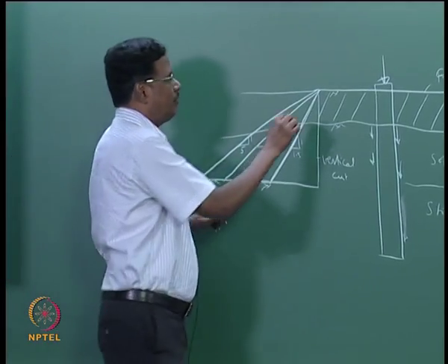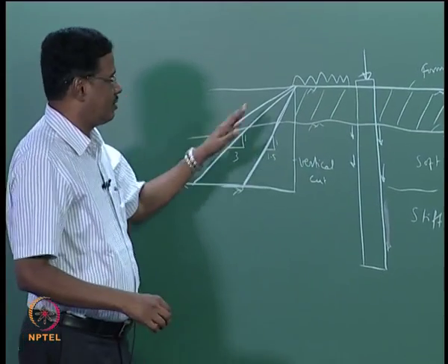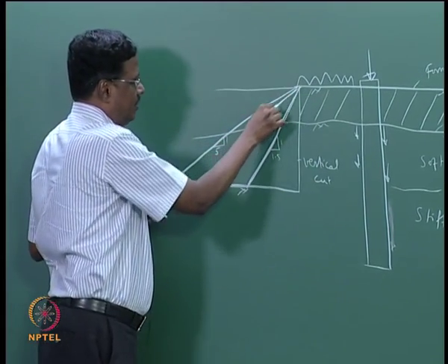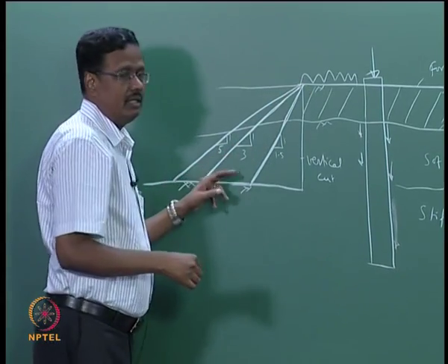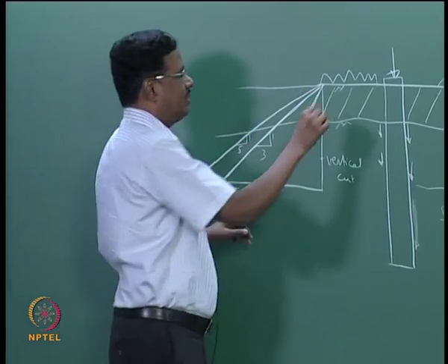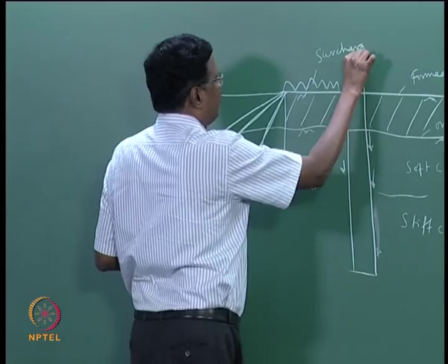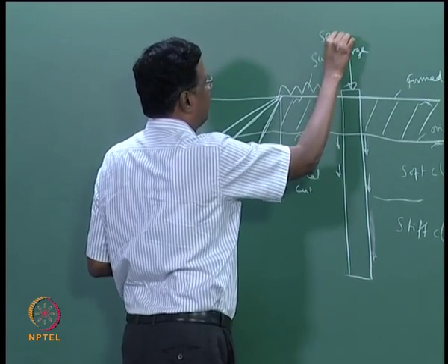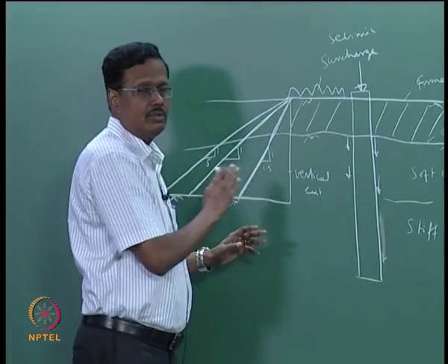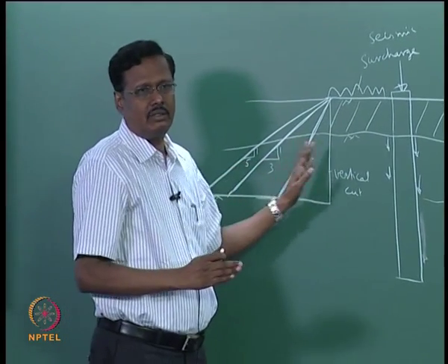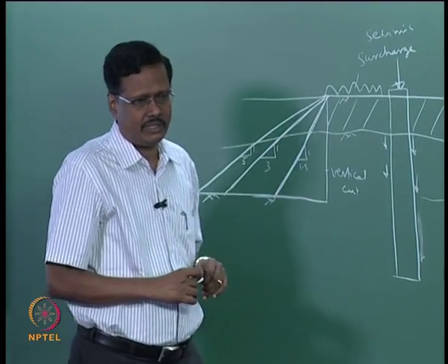But now suppose you put some surcharge load on this, you stack the container, then the slope may fail. If you have excavated like this, the slope will fail, and that failure is to be avoided because of this surcharge load. Another thing is, when you have this seismic condition, the soil which is being retained in the slope will give an acceleration, and due to that also it may fail. So this is one aspect which is to be considered.